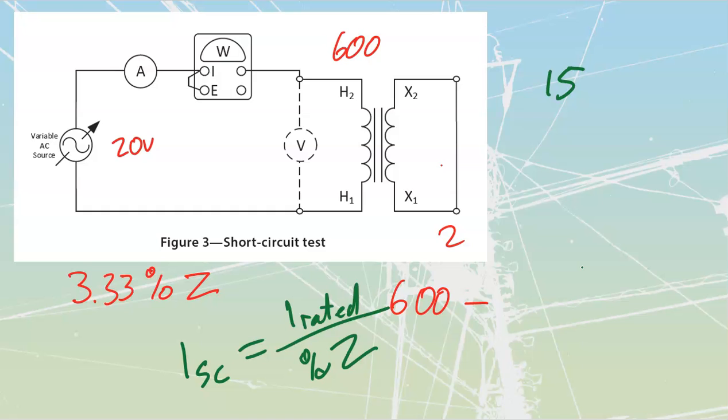They give you another example inside of there where they give you a 100 kVA transformer that is going down to 120 volts on the secondary side, which is 833 amps rated current. Then they ask, what's the percent impedance? They take that 833 divided by that 3% impedance, and they end up at close to 30,000 amps. It's 27 kiloamps that thing could put out. You would once again need to make sure that you can interrupt that rating.